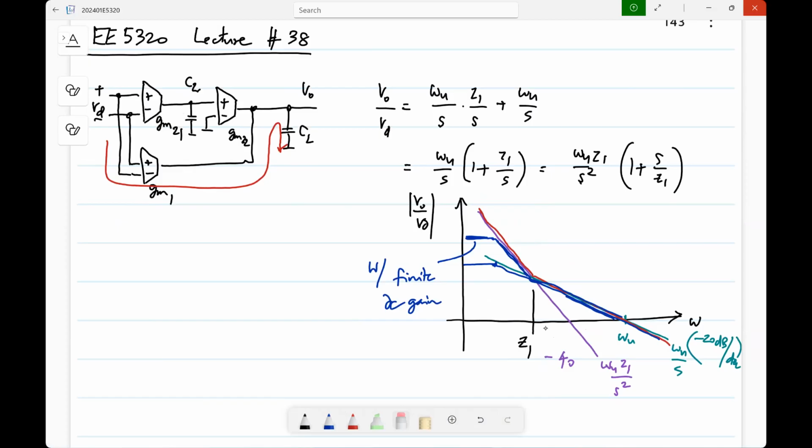Initially it is like this path is not there at all, because you make a unity gain closed loop amplifier and you apply a step. This voltage changes so, this current changes so slowly that it really doesn't count for anything. So it's like having a single stage op-amp reach steady state, and it will reach a wrong steady state based on its own crappy DC gain, right? Now, it's only after this voltage builds up and the current from this cascade of two stages builds up to an appreciable value that you settle to the right steady state. Right steady state meaning lower steady state error.